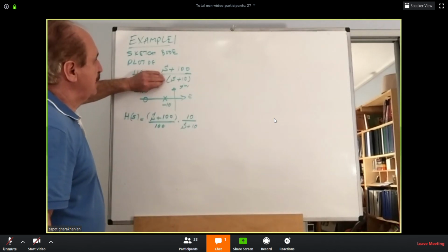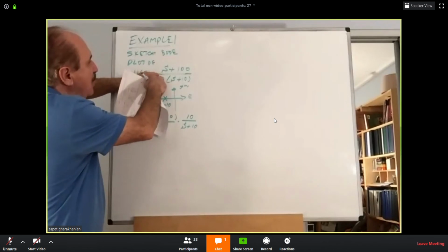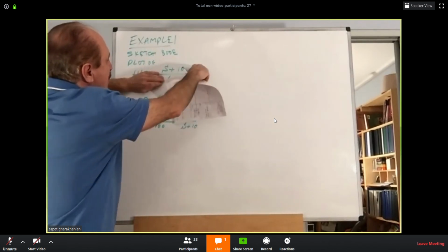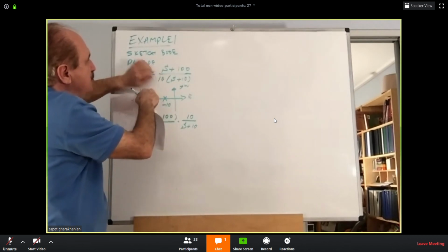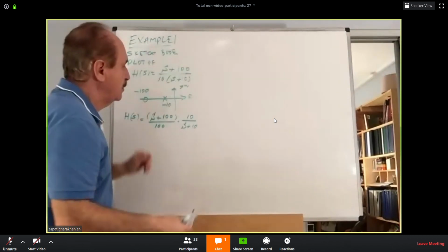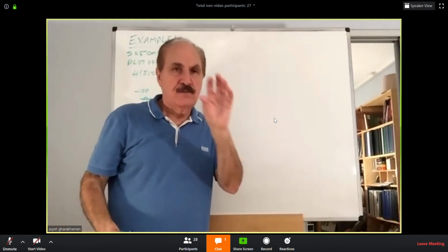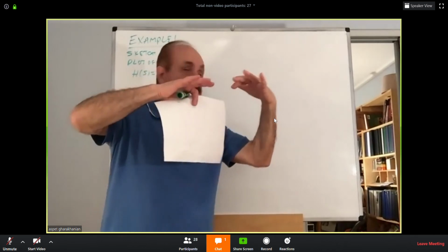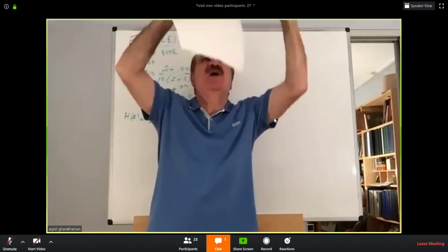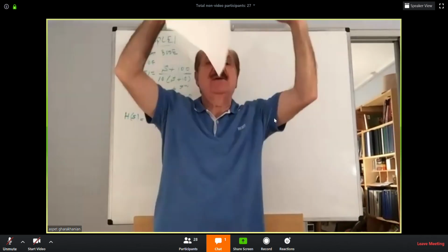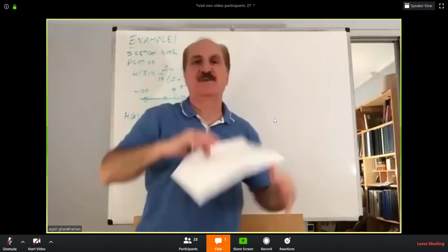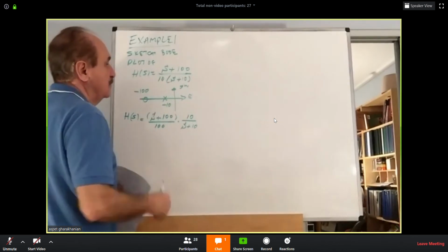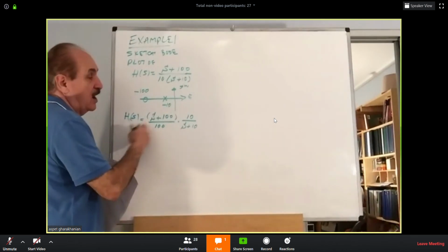So if this was, say, 1, introduce 100 in the denominator, post 100 at the top; introduce a 10 in there, post a 10, so it will be 10 times the whole thing. So you would have a gain. Log of 10 is 20, so all of the graph that you create would shift up by 20 decibels, just moving the picture upward, translating vertically for a constant other than 1.